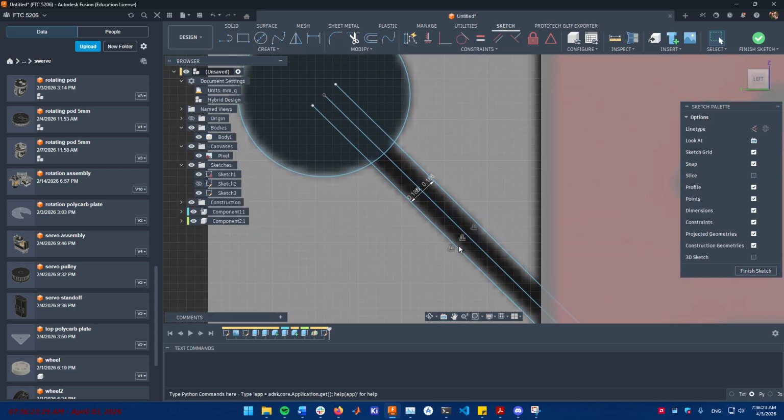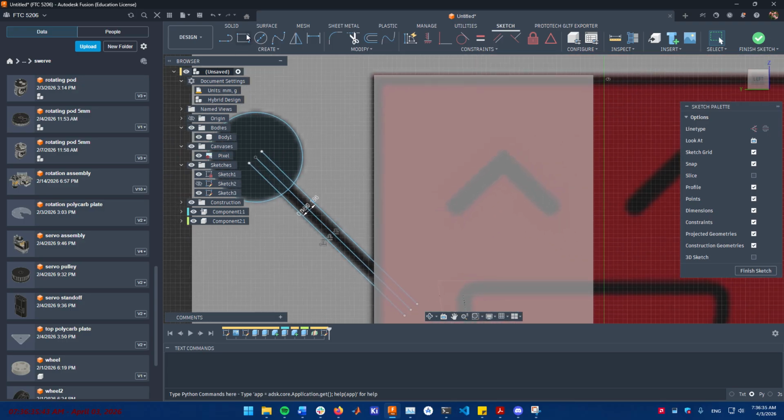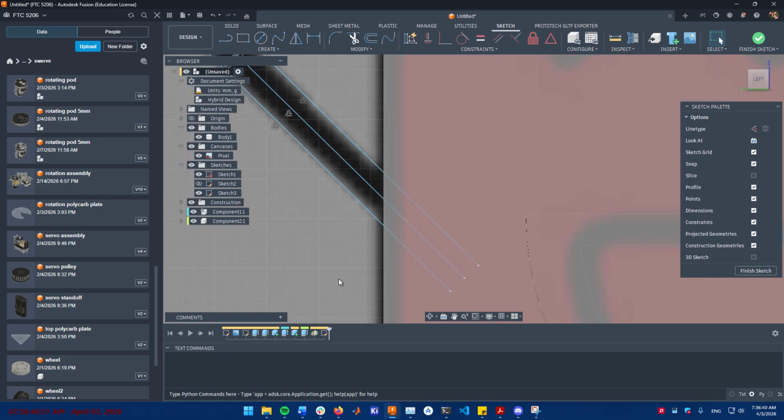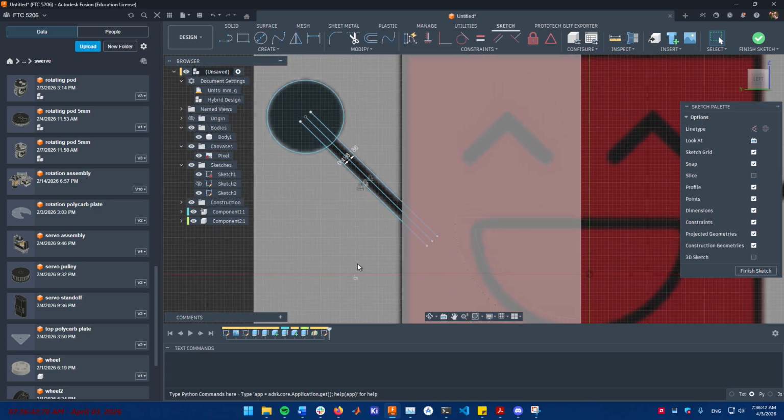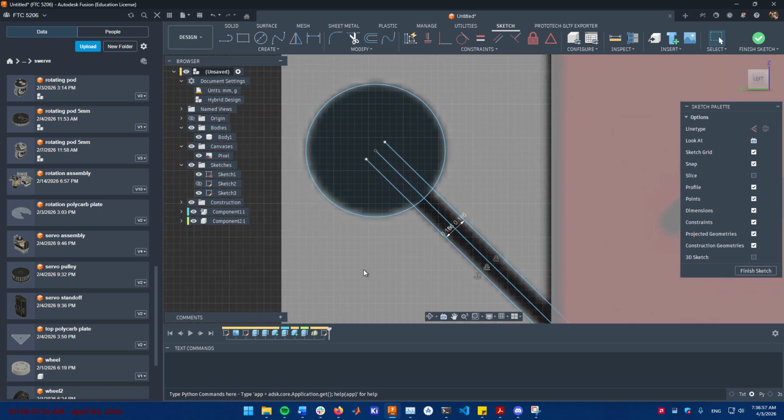And now we're finished with the sketch, right? So we can try to extrude it. But notice how the extrude button always makes a rectangle. But that's not really what we want, is it? So instead of doing that, we are going to make a profile that is half of these geometries, and we will revolve it around the center axis, right? That will make a circle, surely.